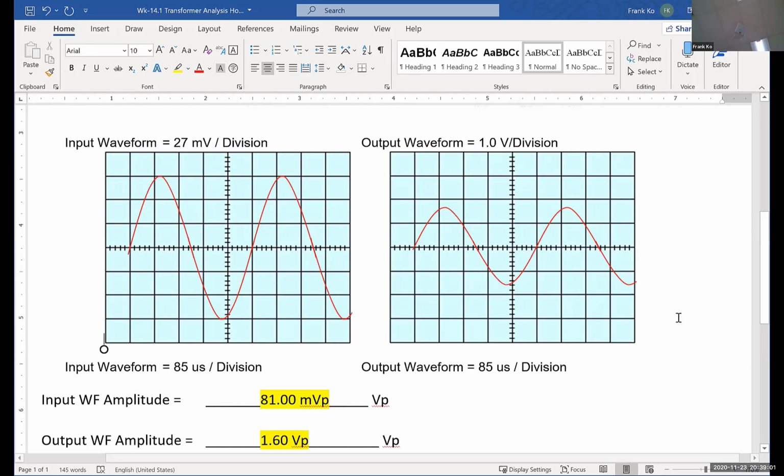All right. Now, based on the waveforms, what do you see there? How many divisions do we count for one cycle, Yusuf? 5. How many people agree we have 5 divisions horizontally for one cycle? And what do you do with those 5 divisions, Yusuf? Multiply them by 85 nanoseconds. Nano or what? What do we see there?